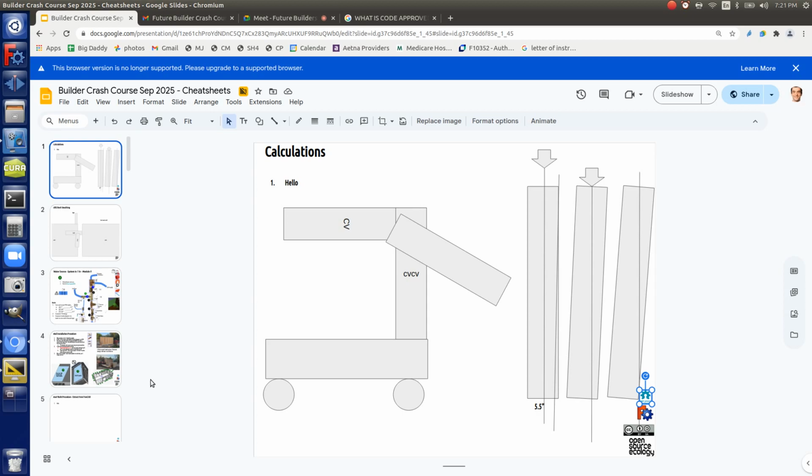Oh yeah, actually, this morning, just to review that little thing, the scabs for when we're scabbing up OSB. We went through a discussion and calculated that the minimum would be 2 inches on each side. That's very common here. But ideally, okay, that's when you use fasteners, but what would be the theoretical limit,